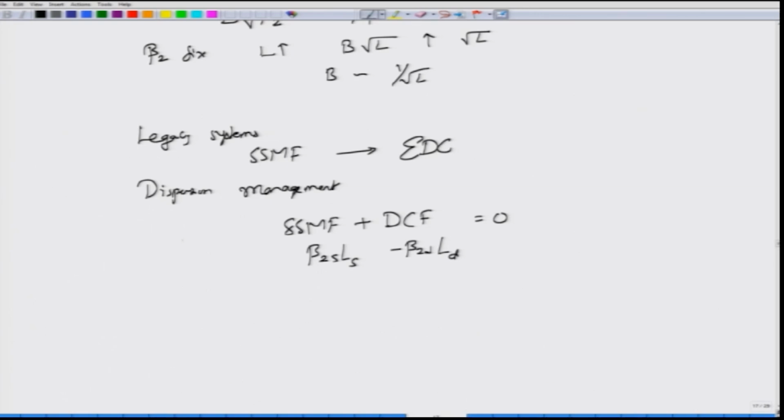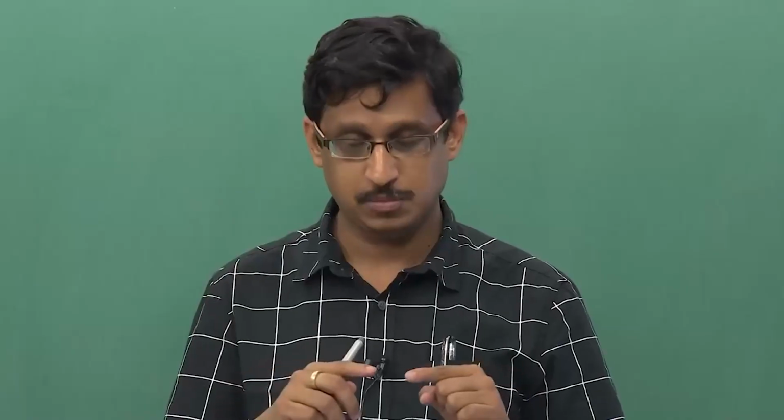Okay. The other way would be to actually let the single mode fiber be completely replaced by a dispersion shifted fiber, and then operate everything at the 0 dispersion wavelength. So, if you operate the transmission system at 0 dispersion wavelength, then the impact of dispersion can be minimized. Okay. These are some simple ways in which we have talked about.